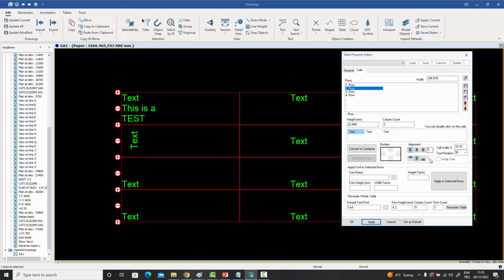And furthermore, offsets can be given to it. And these are features which weren't available before. We can, of course, change the 90-degree to a 180-degree text, which will basically reverse it. Or we can give it a 270-degree text, which will make it look down. So we have these 4 angle options. And if you bring it back to 0, then the text comes back to its original location.